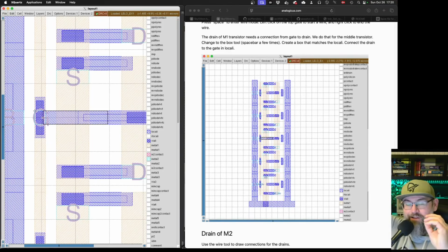And now you end up with one positive hole where there should be an oxygen, a vacancy, and the negative ion of the oxygen that is somewhere else. And these type of oxygen vacancies can also generate possible states for electrons to jump into and change your threshold voltage. Now we don't want any of this. So we kind of want under processing that there is the least amount of charge change.